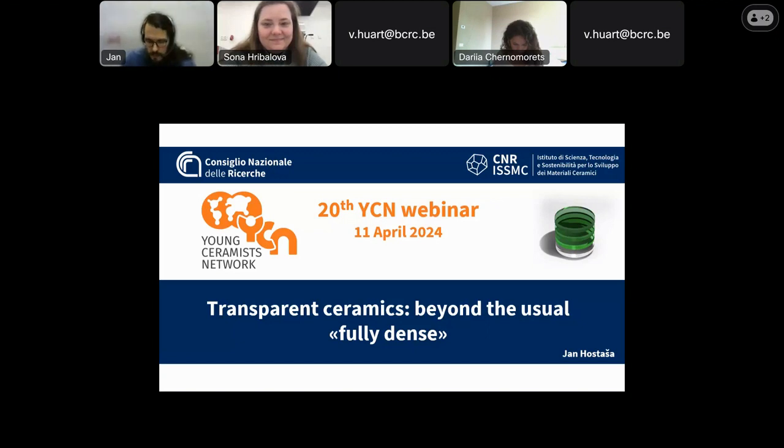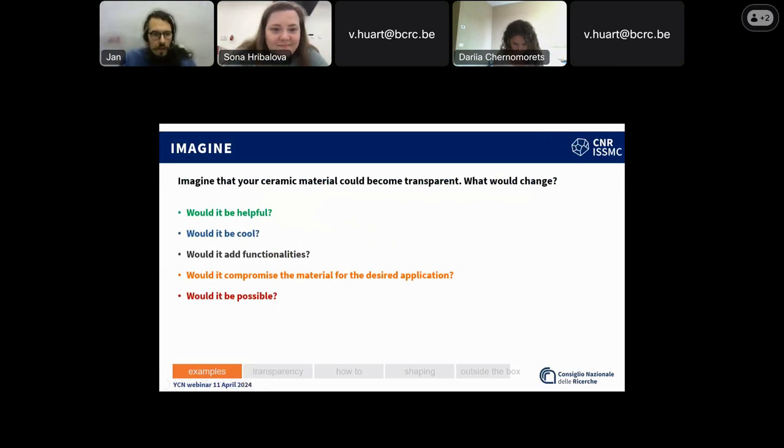So when we talk about the densification, that was already in the title at the beginning, it's really not enough to get to the standard fully dense ceramics. Like if you talk to most ceramists and they say, yeah, my materials actually are fully dense, they are 97% dense. I mean, 97 is pretty good, actually. 99 is even better, and 99 is definitely not enough for transparent ceramics. And okay, where's the trick? How do you get over the missing 1%, right?